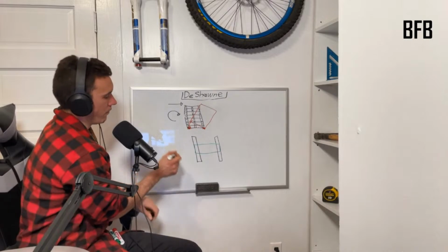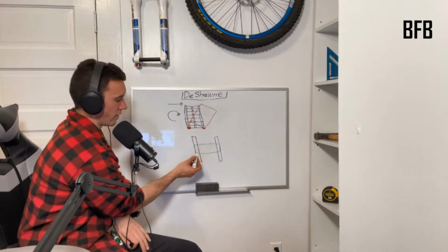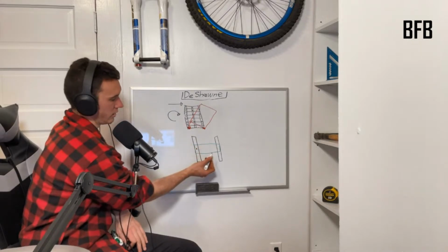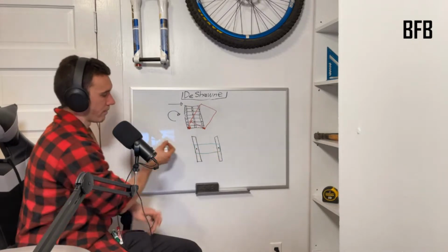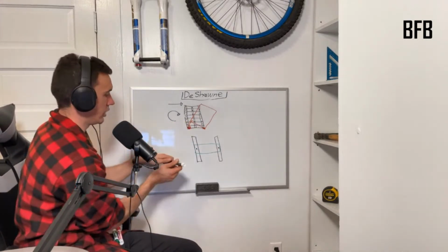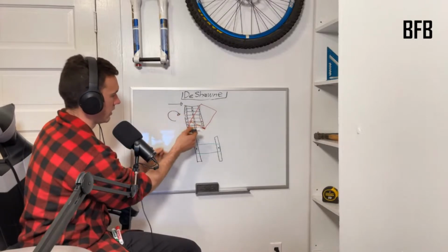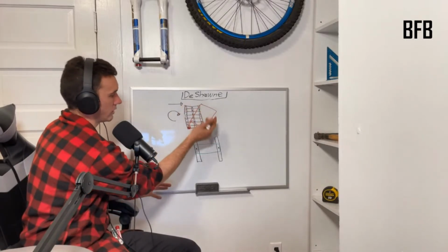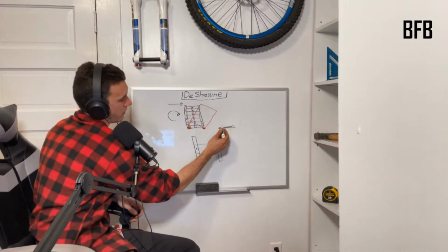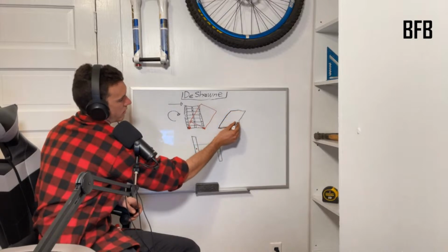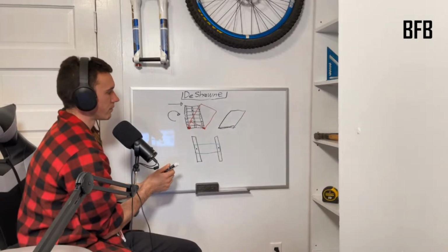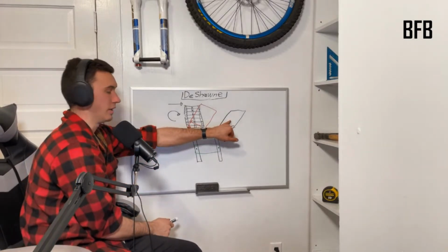All right. So in case A, we're going to install all of our deck planks with one screw in the center of the deck plank on one joist. And the same thing here. Now remember, what we're trying to avoid is this tipping racking action, and the shape change that would happen between this and this if this sheet wasn't here. It would look like a parallelogram, like that. So we're trying to avoid that shape change.